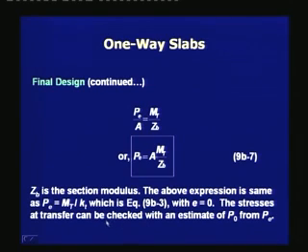The stresses at transfer can be checked with an estimate of P0 from Pe. That means once we have calculated Pe, we can estimate P0 from Pe, and based on P0 we can calculate the stresses at transfer.